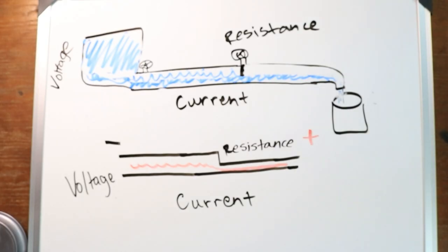So it's very important to know these basic concepts, because when you're on the field and you have to troubleshoot, some devices you have to know. Some devices will be rated 12 volts, and in order to see if that device is working correctly, you have to measure the voltage. You have to say, this thing is rated for 12 volts.